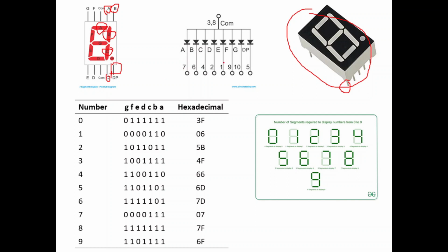Now these are the pin numbers associated with this. This is number 1, 2, 3, 4, 5, then this is 6, 7, 8, 9 and 10. Okay, so these are the pin numbers. Here we have two common pins. Now for displaying 0 on 7 segment display, this one won't be high, and the others are high. As told earlier as well, we are using a common cathode, so we'll be making the other digits high and the hex value will come out as 3F.